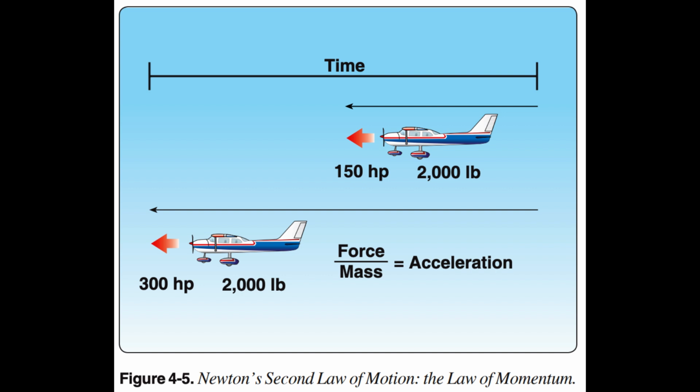This law governs the aircraft's ability to change flight path and speed, which are controlled by attitude, both pitch and bank, and thrust inputs. Speeding up, slowing down, entering climbs or descents, and turning are examples of accelerations that the pilot controls in everyday flight.